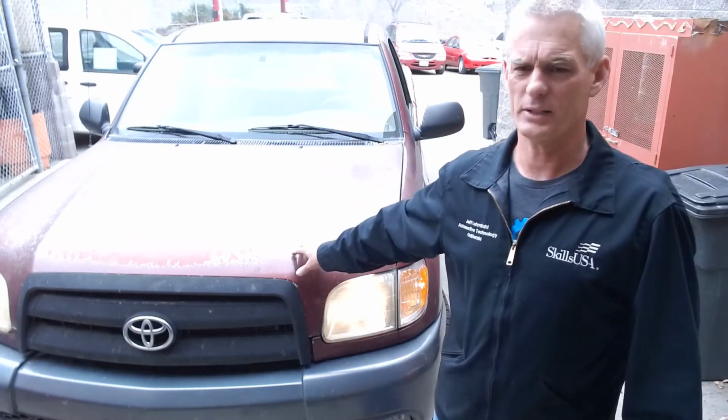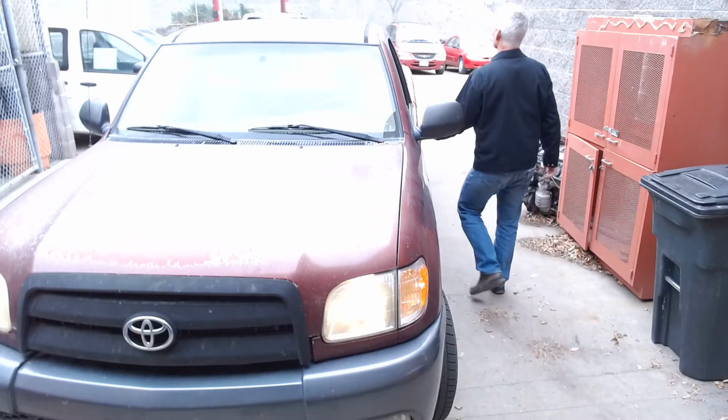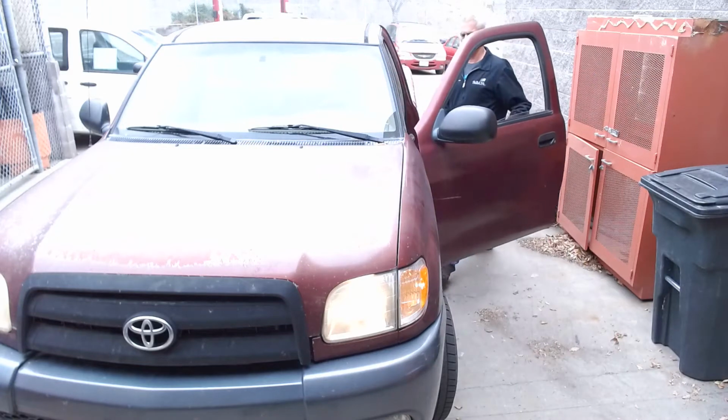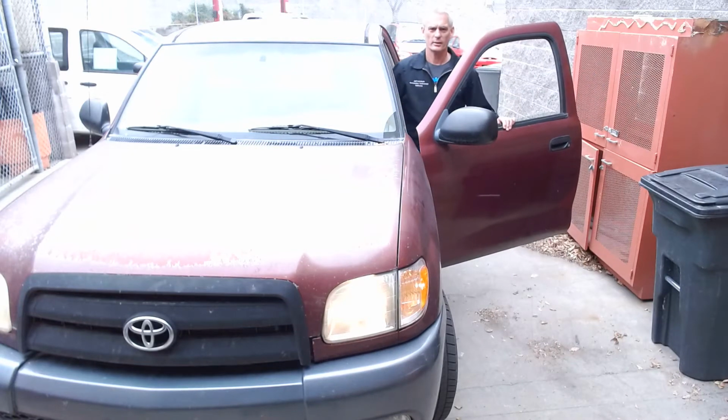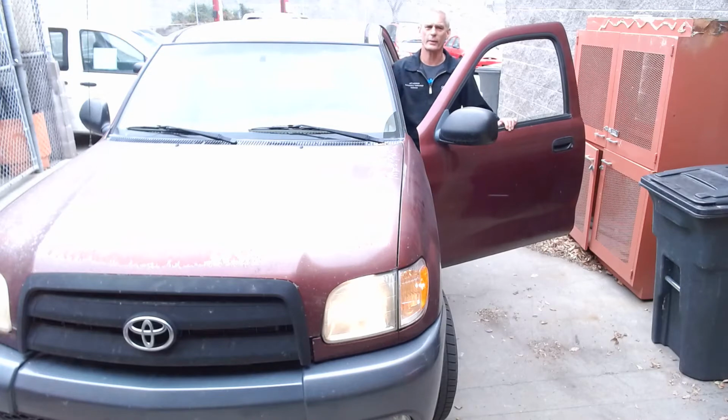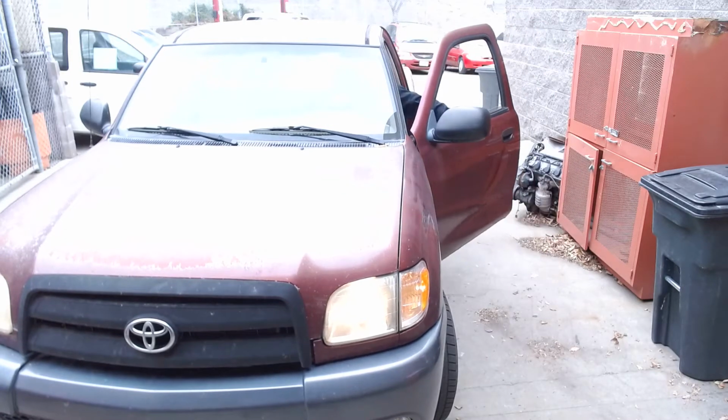Also, hopefully the camera will record the cranking speed. Now there's a tractor up there working. I don't know how much of that's going to block it out. So let's try it. Here we go. This is our headlamp test to decide if the starter motor is doing the right thing, cranking speed's right.